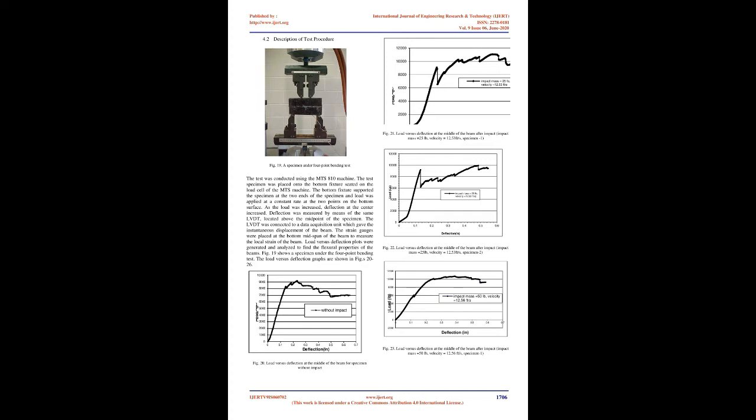In Figs. 9 to 14, the red curve represents the load time history and the black curve represents the energy time history. The load time history has 2 regions, a region of damage initiation and a region of damage propagation. As the load increases during the damage initiation phase, elastic strain energy is accumulated in the specimen and no gross failure takes place, but failure mechanisms on a micro scale such as microbuckling of the fibers on the compression zone or debonding at the fiber matrix interface are possible.